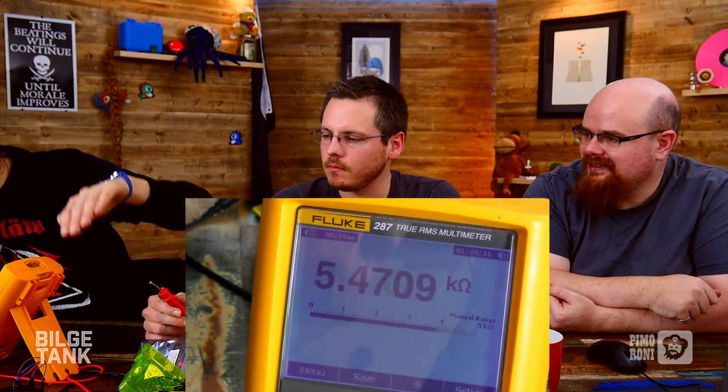Definitely. Okay, so there we go, manual range 5K. There are lots of these analog sensors that you can get, and they're super cheap. Like this LDR will be like 10p or something. They're ridiculously cheap. Things like light-dependent resistors, you've got potentiometers, obviously, which are nice for making interfaces. You've got thermistors for measuring heat, and things like photo transistors. There's all sorts of different sensors that you can use with this method. You just hook them up to an ADC and read the values out.